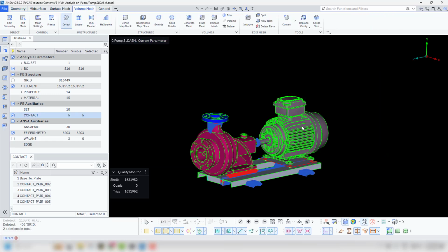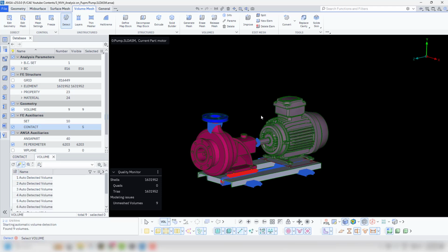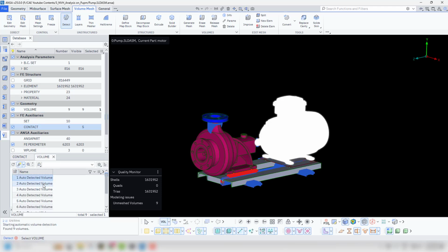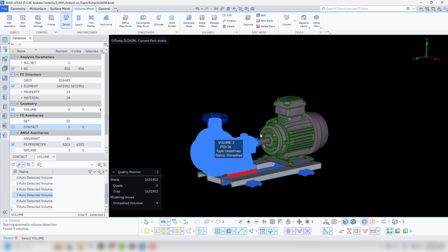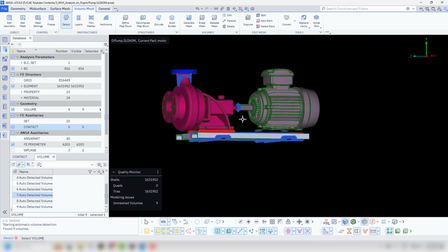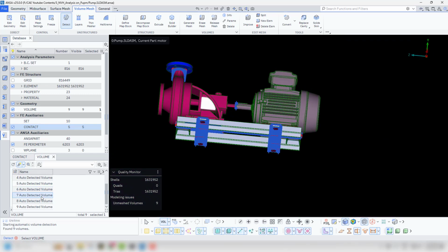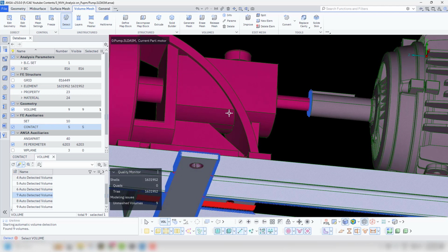Now here how I just meshed it with this shell. Now I just need to recognize the volume so that I can do the solid meshing here. So you could see all the volume. So this is the one which is not needed for me, which is inside. What I can do is, which is beyond the scope of my interest right now, so I can simply delete this.